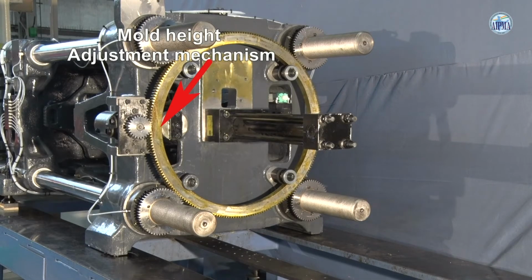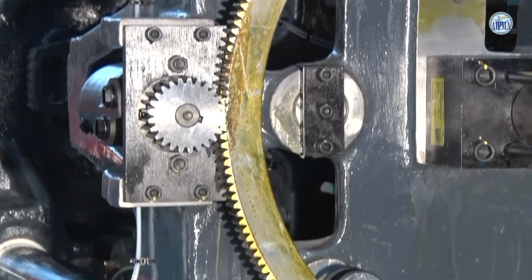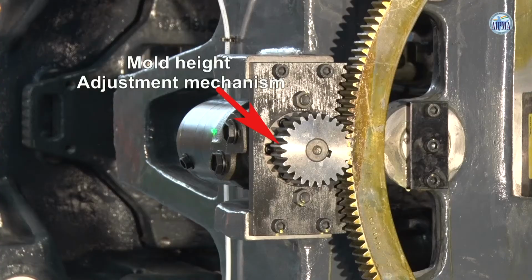Mold height adjustment mechanism. This mechanism is used for movement of die height platen to adjust different mold heights. Hydromotor drives the die height nuts by chain or sun wheel gear system.